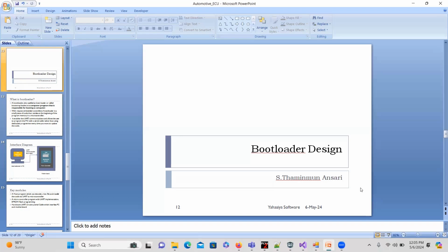Till now, I think we did some 2 sessions, right? In these 2 sessions, we have used only that flasher to flash the software. But this is very tedious, because every time I have to remove the controller from the motherboard and connect it to the flasher, and then I have to load the executable in the software interface and transfer it to the controller for flashing.